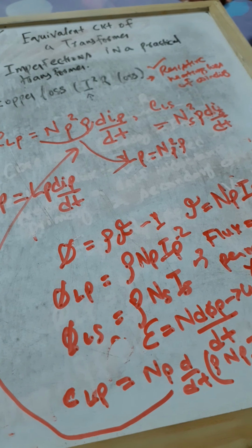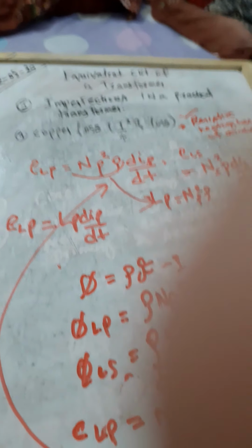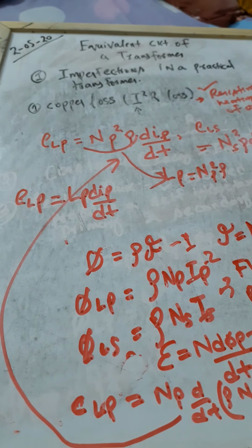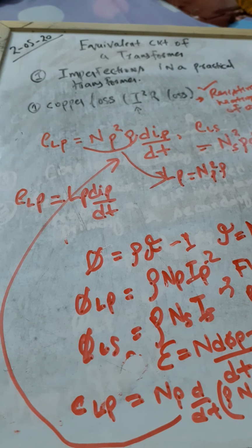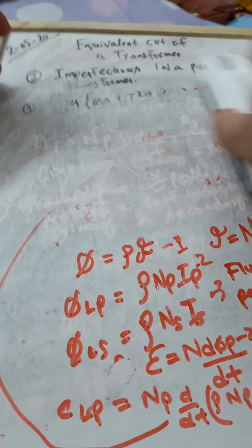So two things you noticed. The number one thing which we have noticed right now is we are getting these equations. One thing was the resistance that was put, the primary and secondary resistance due to the winding. Now due to the leakage flux there is self inductance. You can see self inductance is both in the primary and the secondary side. So you can account for the modeling of your transformer.